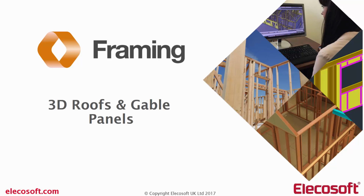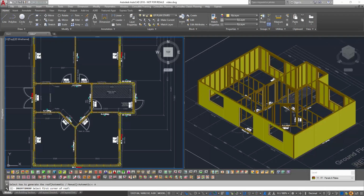Hello and welcome to a short video demonstrating how to insert 3D roofs and gable panels within the framing software. Within the framing software, it is easy to add and merge 3D roofs and then insert gable panels with windows and doors. For this demonstration, I'm going to insert a 3D roof and gable panels to this small house drawing. I will then go on to adding windows and doors, and finally internal wall panels and ceiling.